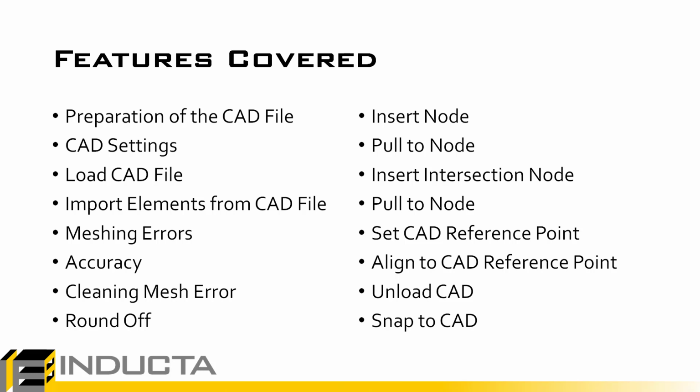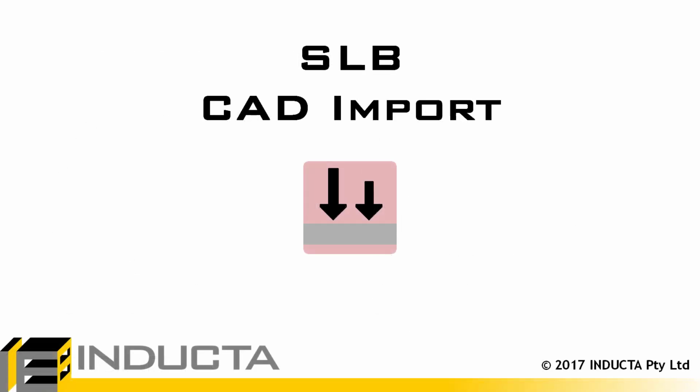Now, it should be noted that this essentially was an idealized case, a best case scenario where the CAD file was cleaned up in a very nice manner that made it easy to import. Now, it will often be the case where we are unable to import CAD files that are cleaned up so nicely, hence we will get many more meshing errors. Or the geometry will be much more complex, which in itself will cause meshing errors. And some of the editing tools that we touched upon today, we'll have to use them a lot more, or use some different editing tools to clean these meshing errors up. Now, cleaning up of meshing errors will be the topic of the next videos.